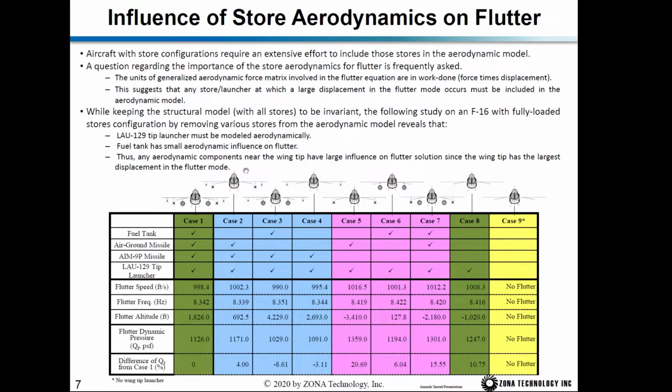And the next thing we want to talk about is the influence of underwing store aerodynamics on Flutter. An aircraft with store configurations requires an extensive effort to model all the stores in the aerodynamic model. So sometimes we want to say, okay, if some of the stores have little impact on the Flutter solution, we do not need to include them in the aerodynamic model.